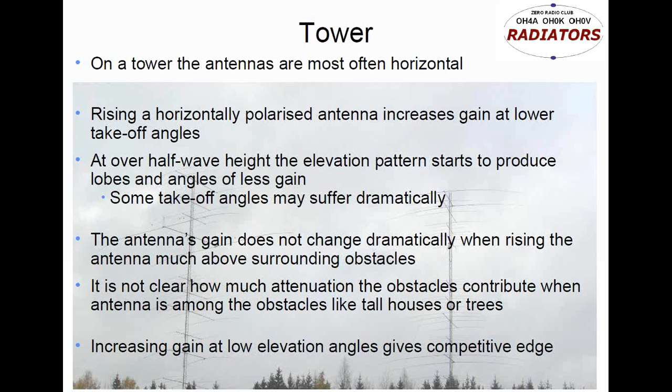If you go with your antenna to about 10 meters height, then you are going to have some losses of gain at some takeoff angles. The antenna's gain itself does not really change, but the main lobe will be going downwards, and then there will be some dips in the gain.